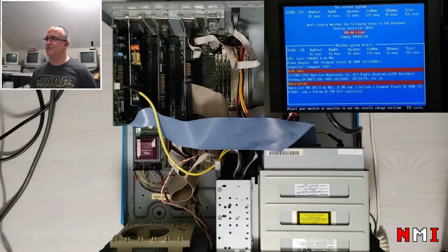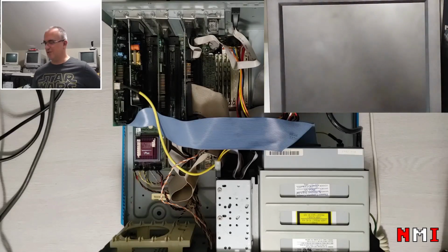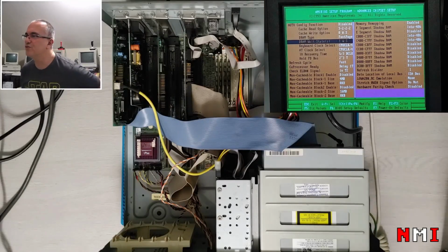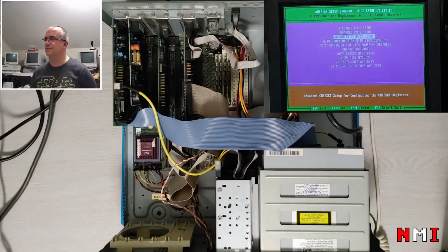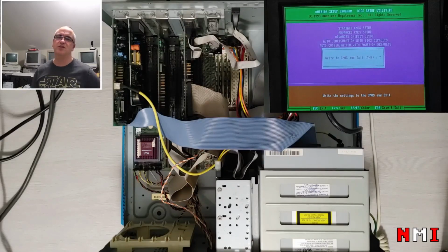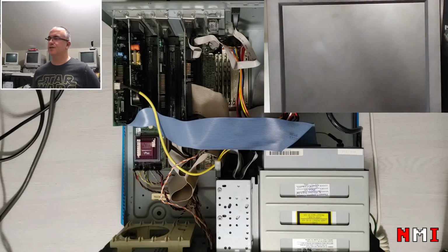Okay, 139, right? Let's try something else. I think there was another wait state there. Here, yeah. Oh, this is for the DRAM. Yeah, let's try 0 wait state. The worst that can happen is that it doesn't work and then I revert.